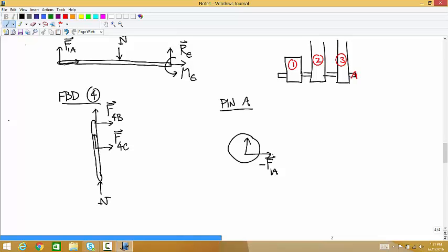And now we're going to use that two-force member simplification. The other two forces, we're treating member 2 and member 3 like they're cables, because we know the direction of those forces. So we have one force here that I'll call F2, and one force here called F3. We know the directions of those, so we can figure out the unit vectors for those.